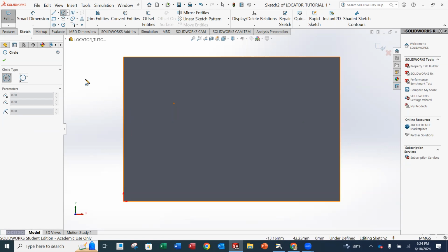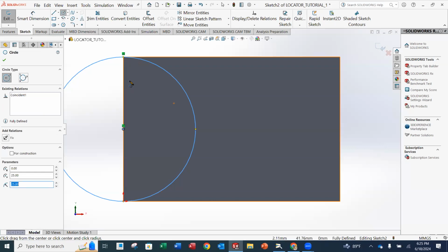Notice I have a circle on the end of my pencil, and I'm going to go along this line until it activates and I see the center point of it. That's going to be the midpoint. That is where I want to activate the center of my circle. So I'm going to start there at the midpoint of that line, and then I'm going to activate and get to the end point of that line. See where that orange circle is activating that end point? I'm going to click that. Now, why do I want to do that?